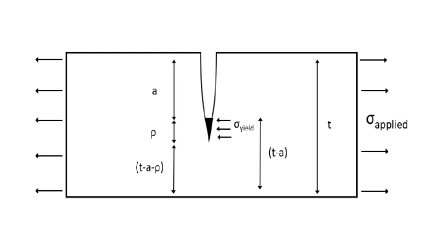At the end of that part-through wall crack, we have a small zone which we call the plastic zone, and then we have a remaining ligament, an elastic ligament after that. Now, if you look back at the history of fracture mechanics model development, you'll come across something called the strip yield model. The strip yield model was developed in the 1960s by a couple of fellows named Barenblatt and Dugdale. Now what they did is they came up with a way to approximate elastic plastic behavior using linear elastic fracture mechanics.